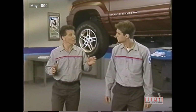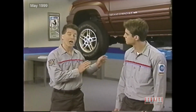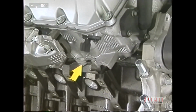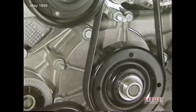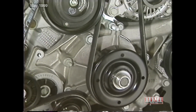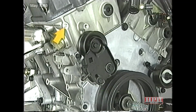Our inspection of the engine compartment didn't reveal the source of the leak, so now we're going to look under the engine to see if we can find any leaks here. We'll begin by checking the sealing between the cylinder heads and the block. Next, to make sure that the gasket for the timing chain cover is sealing properly, we'll inspect the area around the cover for signs of oil, and check for leaks around the oil gallery plugs.